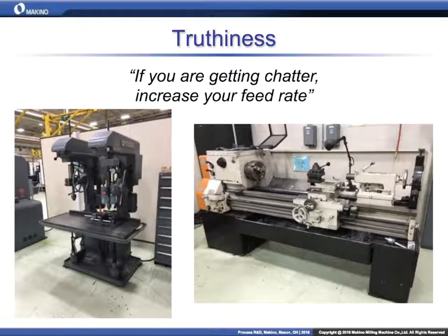And then we're just guessing, but we're thinking this may have come up where you're on a machine and you're just kind of babying a cut into something. You've got to make one part, you're getting it through, and you could be getting chatter just because you're not pushing on it. You're just not aggressively engaging the material enough to create a thick chip. Right. You spend a lot of time rubbing. And this can happen anytime someone's a little bit tentative about machining. They could just get this squealing, as we talked about up front. We got quite a bit of chatter from running real low chip thickness.